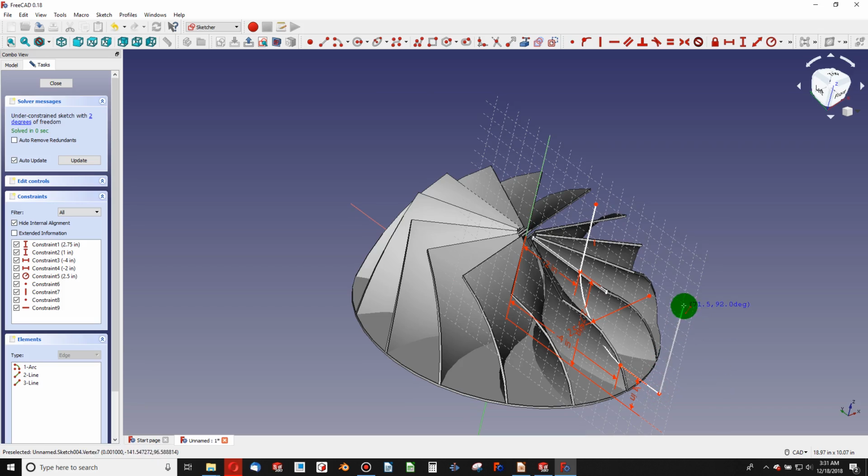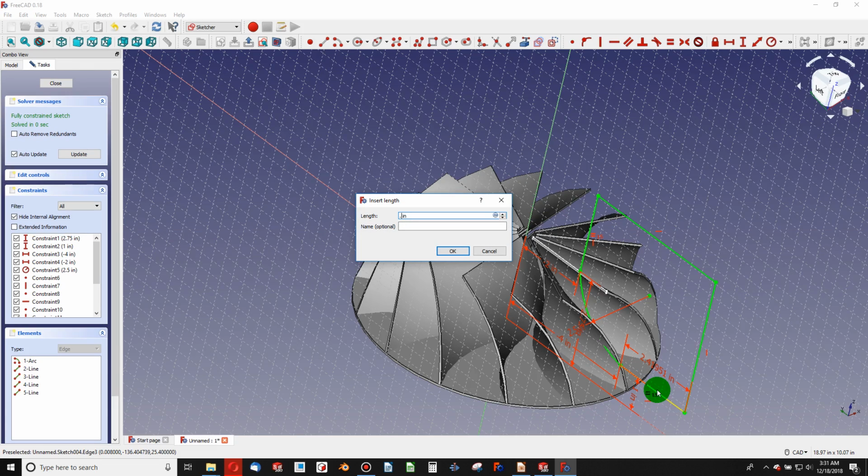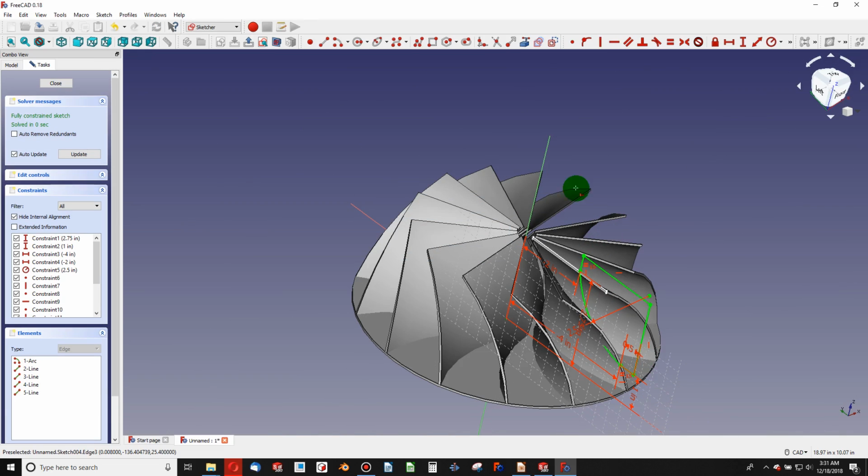horizontal. Again, should have used polyline for this. It's a hard habit to get into, and of course, I could do polyline, but now I've got one line to draw. SolidWorks kind of defaults to polyline, and so I naturally just grab a line thinking it's polyline. We'll make here and here equal, and we'll give this a dimension of 0.5.